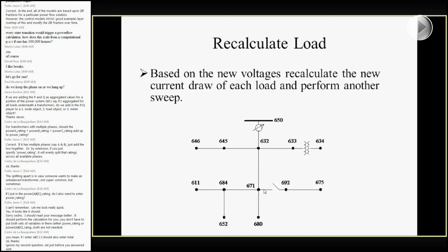Obviously, you can adjust that convergence criteria depending on how stringent you want your convergence to be and how accurate you want your system representation to be. GridLAB-D also has the ability to specify individual convergence checks. It's not supported anymore, but we used to have a Gauss-Seidel solver in here, and one of the ways to actually get that to work better was if you put tighter convergence criteria on these main trunk nodes, and then looser ones on the end-of-line ones, you could actually get faster convergence on your system. So that's still a trick you can do with forward back sweep and even the Newton-Raphson one.